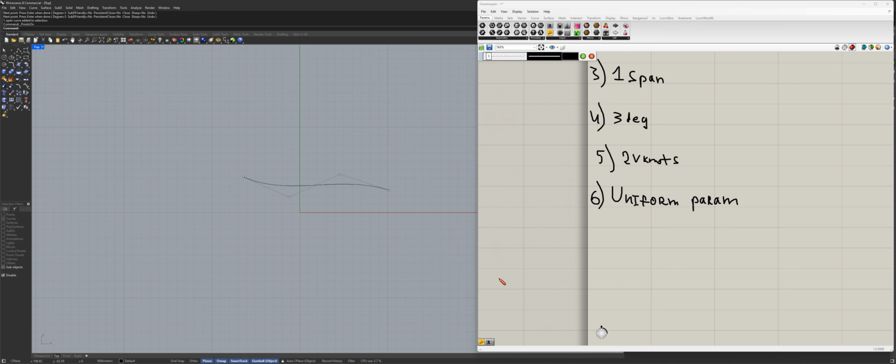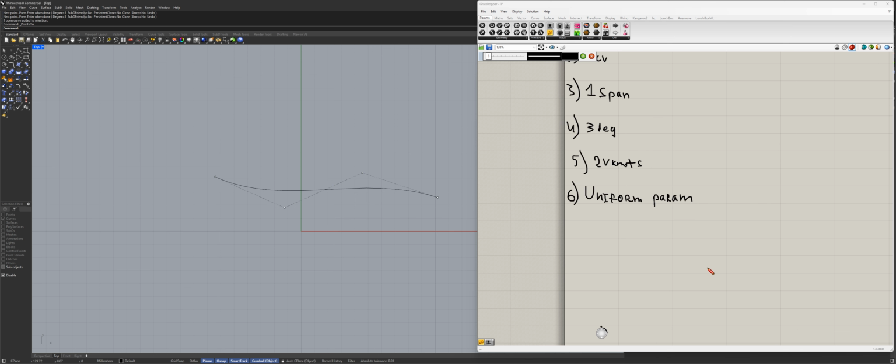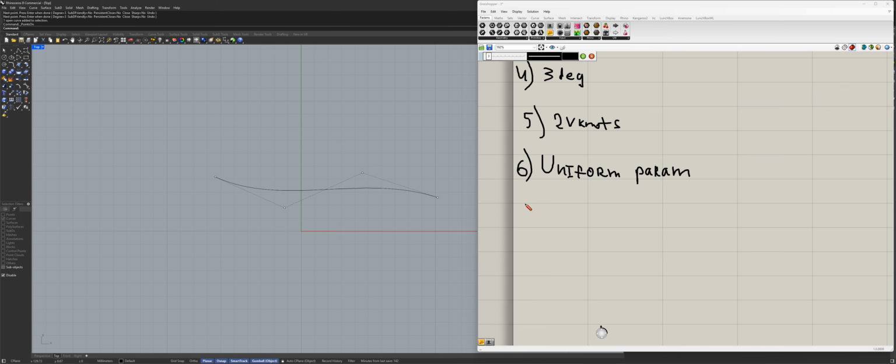What else can I say? Well, I can say that this curve is clamped. What does it mean? If you look at the curve, it starts where the first control point is and ends where the last control point ends. So it's effectively clamped at the beginning and the end. The other control points are not clamped because they're not coincident to the curve, which is standard. So it's safe to say that this curve is clamped, and yes, it is. So clamped at start and end.